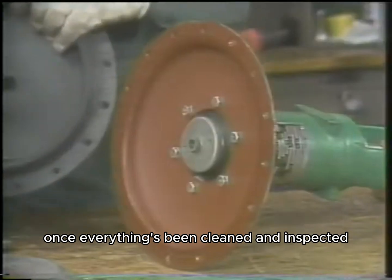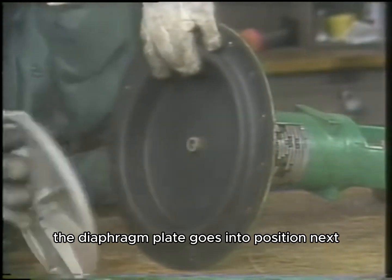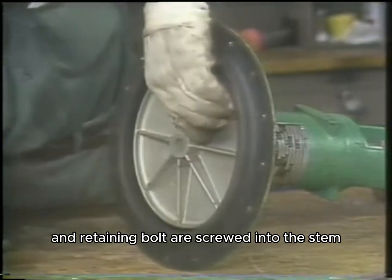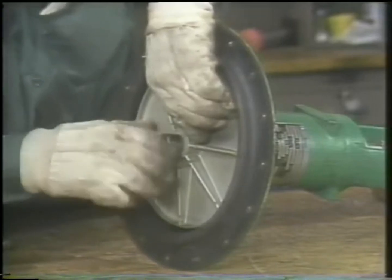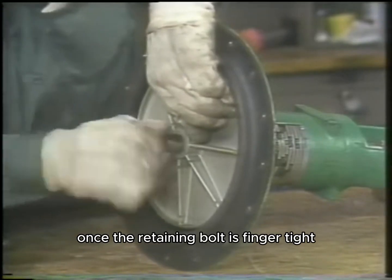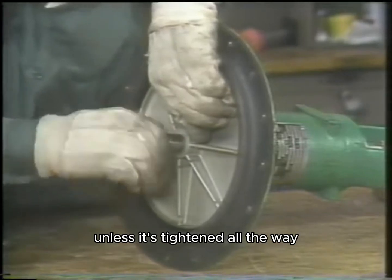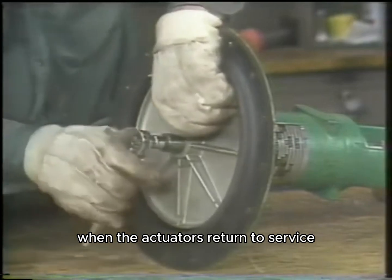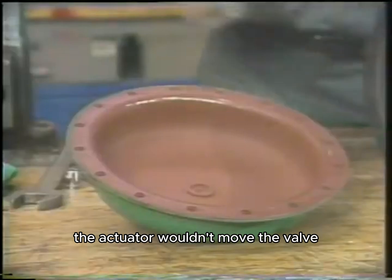Once everything's been cleaned and inspected, a new diaphragm can be installed. The diaphragm plate goes into position next. Then the spacer and retaining bolt are screwed into the stem to hold everything in place. Once the retaining bolt is finger tight, it's fully tightened with a wrench. Unless it's tightened all the way, free play will result in inaccurate positioning when the actuators return to service. And if it came loose, the actuator wouldn't move the valve.